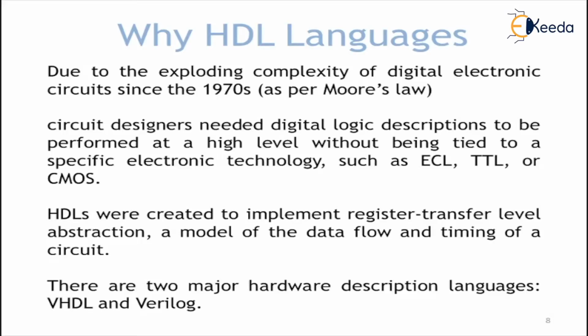Because of that the design becomes very complex. It would be very difficult to draw on paper because the gate counts are more than 10,000, then lakhs, going into the millions, and nowadays billions. So we cannot do this many circuit designs at paper level. Because of this, VHDL or HDL languages come into the picture.